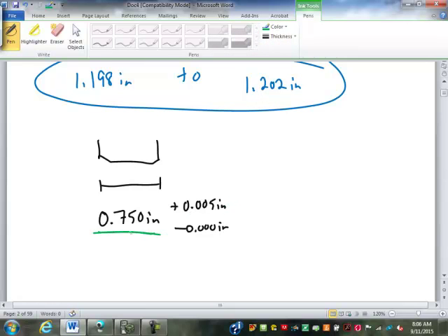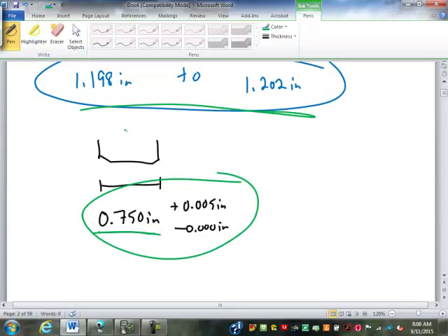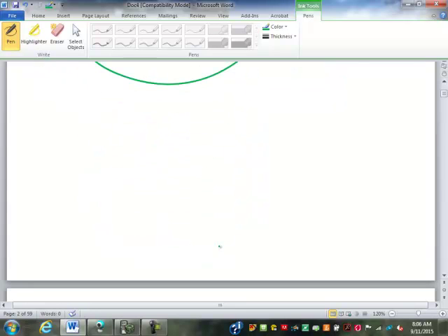We really prefer it to be exactly 3/4 of an inch, but we can be off a little bit larger. And remember, we talked about why we would do this over just creating the equivalent bilateral tolerance. This is telling us that we really want it closest to this. We don't want it right in the middle of the range. We really want it closer to the bottom end if we can.